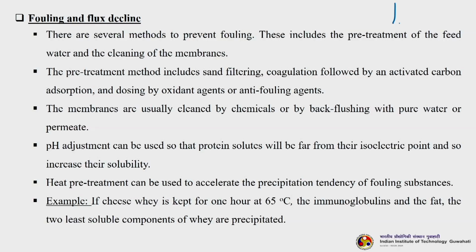If we do not remove that, then the plugging of the pores of the ultrafiltration membrane will become very fast, and there will be huge fouling and concentration build up, and your flux decline will be very fast. Almost it will decline something like this, which we do not want. We always want a flux decline profile something like this.